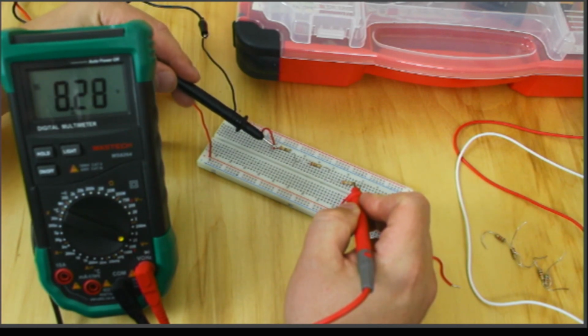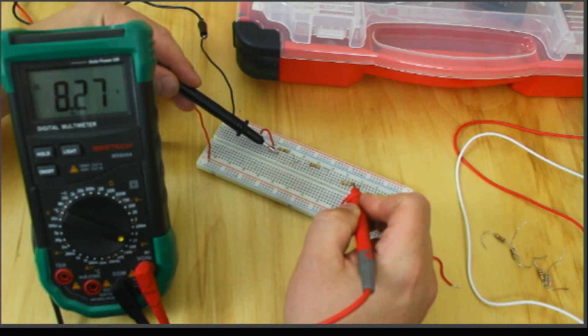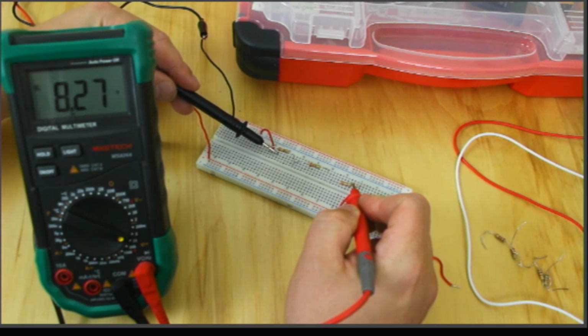So the 9.4 volts that I was using before, that's incorrect. What I should have done is measured it right now while it's sort of under load to see how it would be performing, because it is no longer 9.4. As I said, I must have left it connected or something, because it drained 1.2 volts out of it.